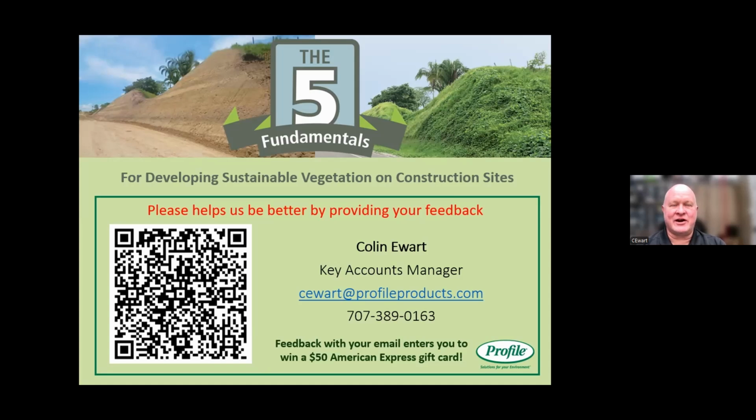Typically, if you're going to see nitrogen runoff, it's going to be as a result of fertilizer that's being put in as an amendment. Even though we are using HPGM, we're adjusting that nitrogen cycling process in the topsoil horizon and introducing organic matter. So you can be adding an inorganic fertilizer, a 777 or whatever it happens to be, to that mix. That's where I'd have the caveat. If you're concerned about that, make sure any fertilizer being added is a slow release fertilizer.